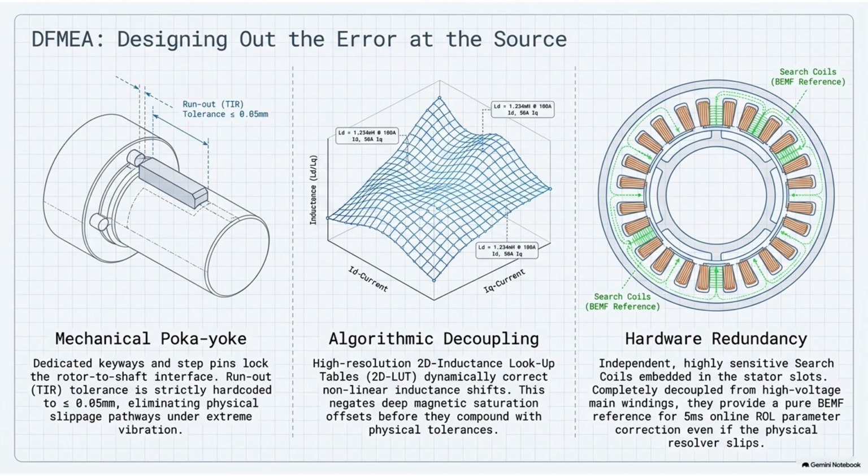Why 720? Because 720 volts is the absolute physical ceiling for the components in this specific architecture. If the unregulated voltage from that spinning motor spikes above 720, you experience EOS, electrical overstress. Which means? The incredibly expensive silicon carbide chips in the main inverter will physically melt. The high-voltage wiring harness will ignite. Oh, man. The stepwise ASC sacrifices the smooth driving experience, pops a massive electrical parachute, keeps the voltage under 720 volts, prevents a catastrophic fire, and allows the heavy mechanical mass of the car to safely glide to a halt. It's a spectacular safety net.